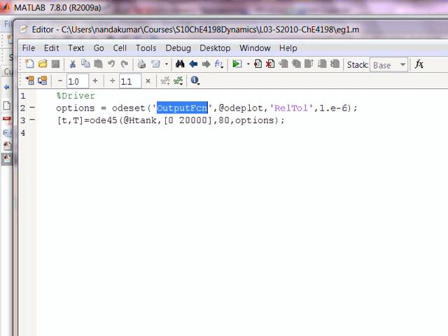Yeah, sorry. That's the second argument in that. Relative tolerance. It simply says what is the error that I'm able to accept in the temperature profile. The temperature profile should be accurate to about 6 digits, for example. It uses that information to find what time step it should take. This is a numerical methods question because the error depends on the time step that you take. So here all you're saying is give me an accurate solution.